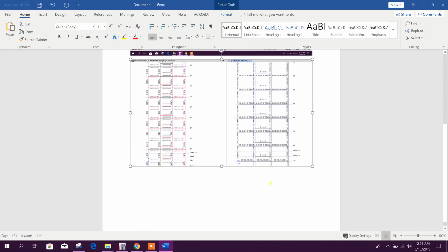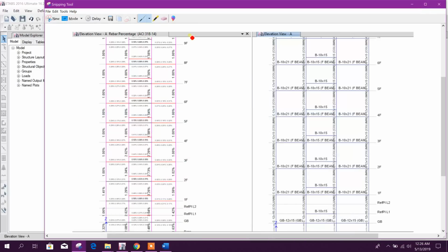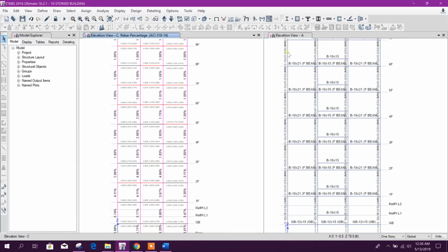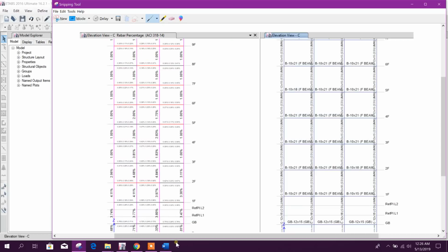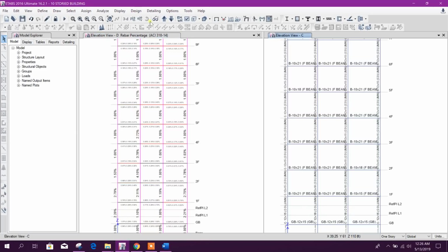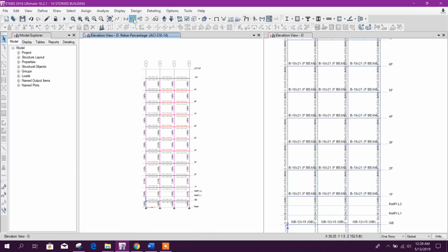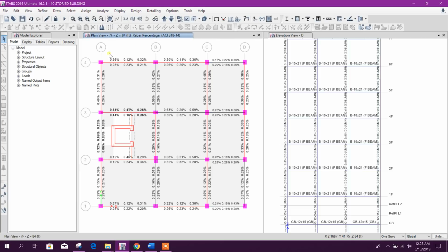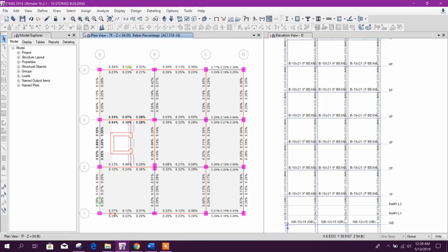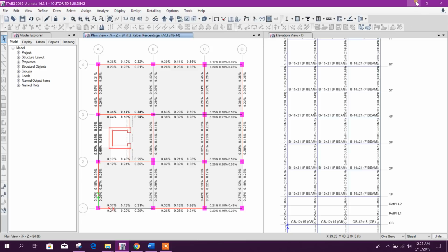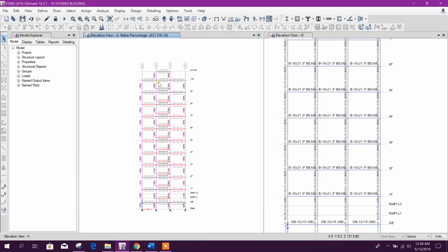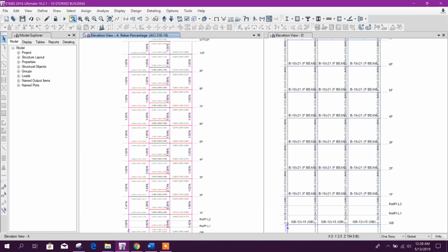In this way, after finishing all the grids, as our structural plan up to A, B, C, D grids covers all the columns, the elevations are enough for column section checking. Now here we will go to grid A, unlock the model.